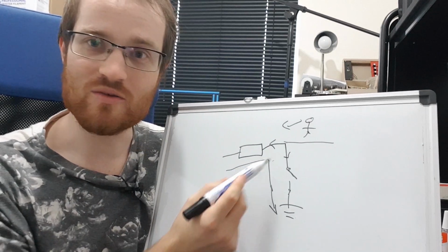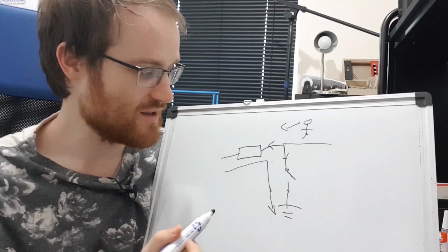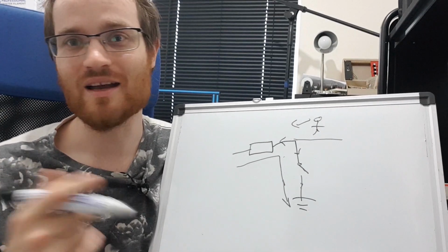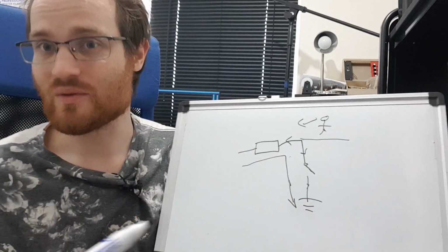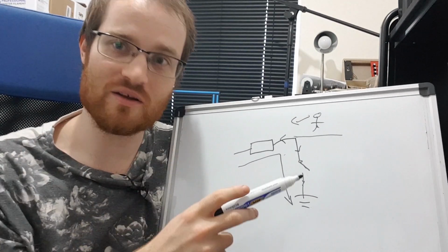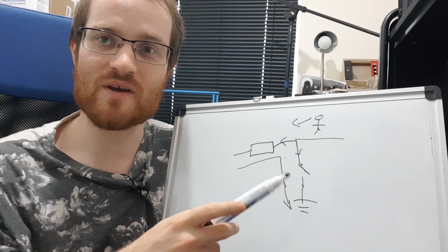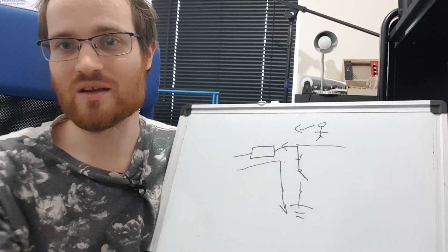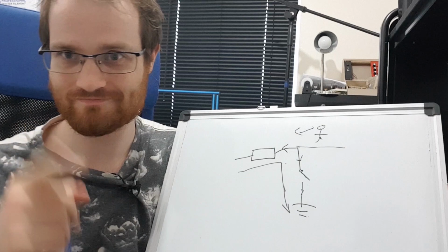So if we know R, we know the worst case output impedance, which is the only output impedance we care about. If we design for the worst case, then it will only be better than that. And we know R is our worst case input impedance, and we design for that, and it'll only be better than that. So whenever you're looking at any circuit and thinking about input impedances or output impedances, think about how bad can it get, what's my signal extreme, what's my lowest frequency, what's my highest frequency, and think about how your circuit is going to react, and then you don't even need to go into all the maths and all the complicated impedance and complex numbers and all this kind of stuff. You can just build up an intuition for it like this. So back to the normal video.